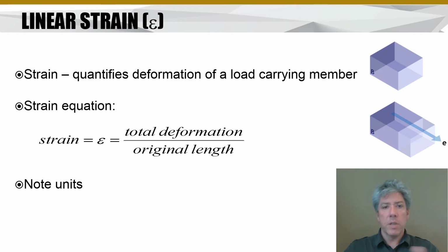Unless, of course, you've strained it so much. I shouldn't say it's always. It starts off less than 1. It can go more than 1, especially in the case of a rubber band. If I have a rubber band that's 1 inch long and I strain it such that it is now 3 inches long, well, then the deformation is 2 inches over the original length of 1, and so strain can go to something like 2.